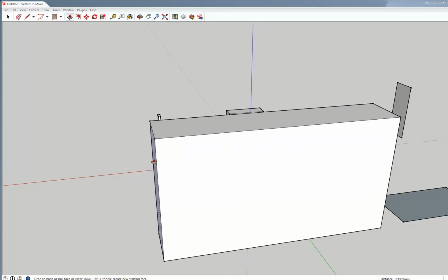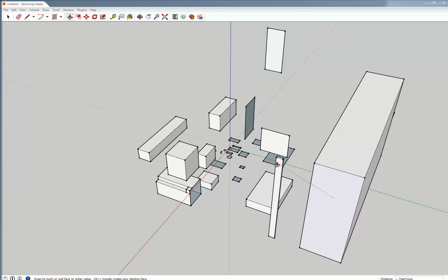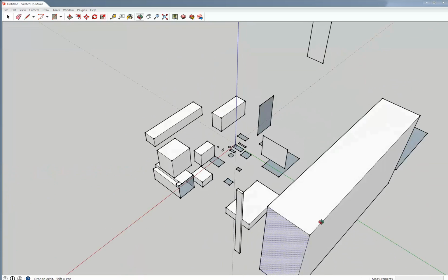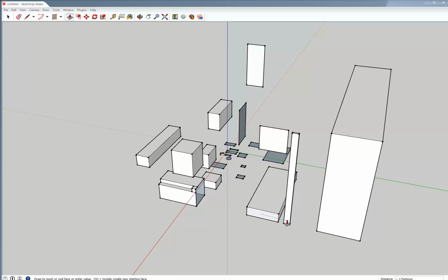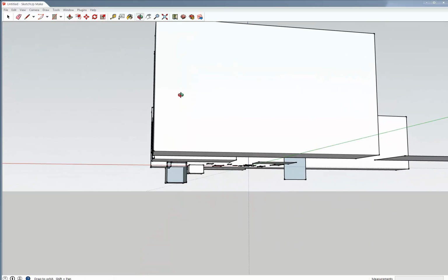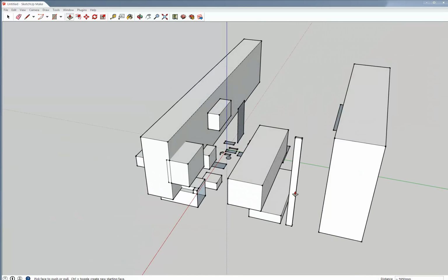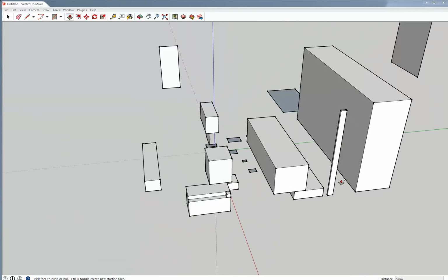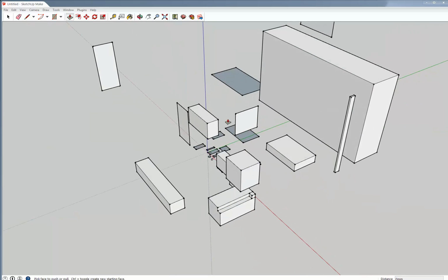So see I'm pulling this out, but I want to line up exactly with this point over here. So you can actually just hover over that point and it'll draw a dashed line, and now they're exactly the same distance. Yeah, so you can sort of have everything lining up along that point. And Command Z just undoes all that stuff as well. Command or Control Z, depending on whether you're in Mac or Windows.